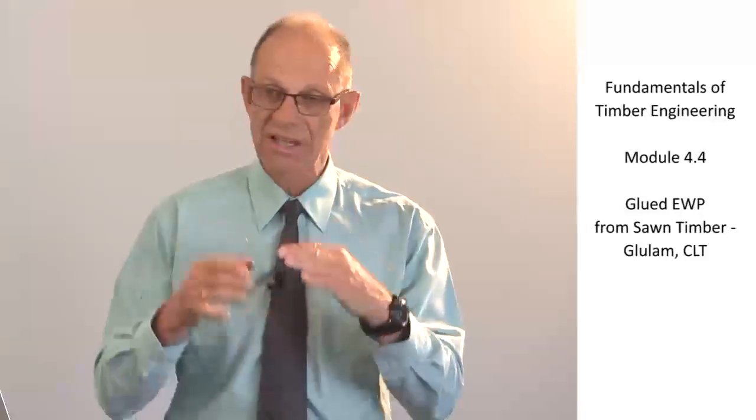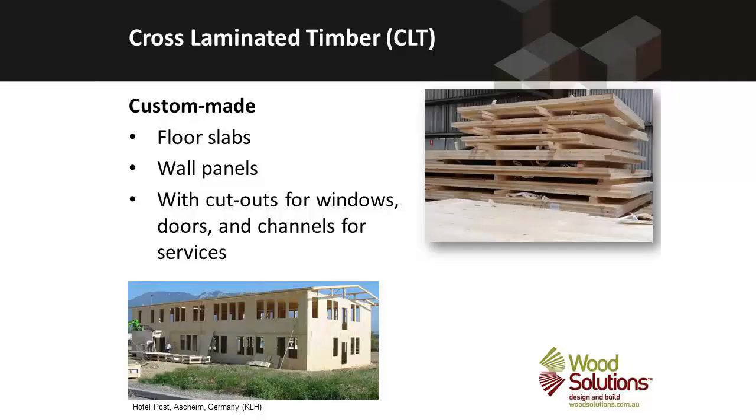They are good at carrying out-of-plane loads, and they are good at carrying in-plane loads. So when we look at the type of structure shown in the lower photograph of this slide, it shows panels which have capacity to carry lateral forces as structural elements in that building. The whole building arrives as a flat pack, as shown in the upper right-hand picture of that slide.